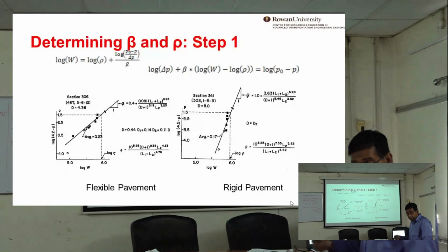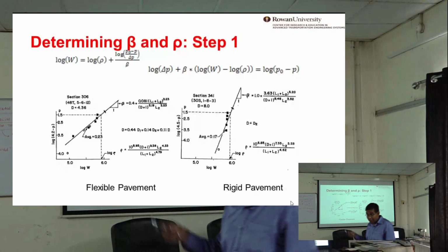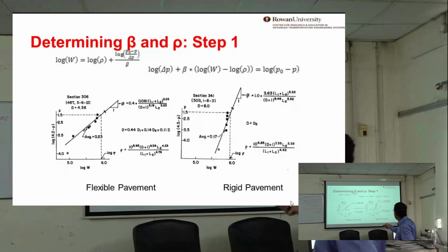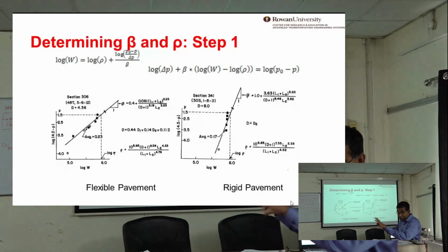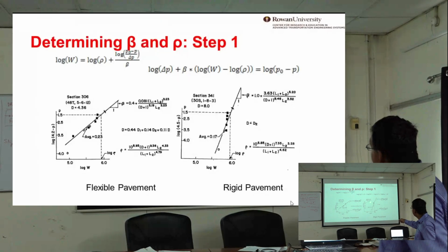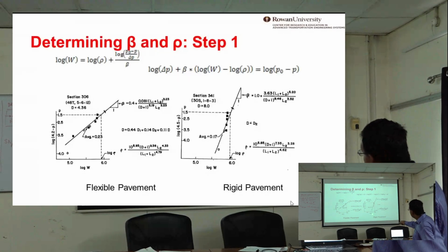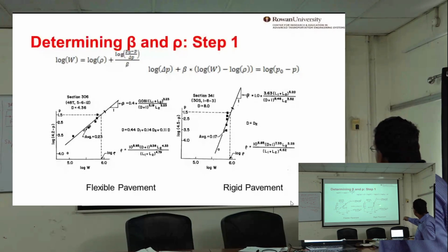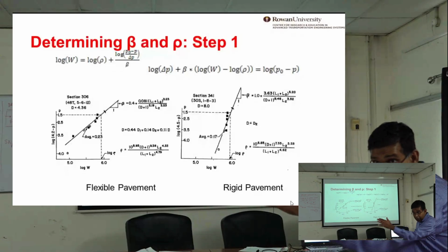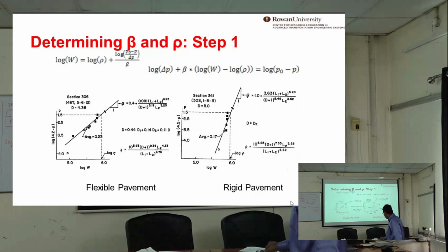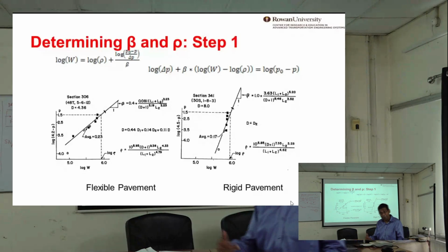So someone was asking me about the model, but this is really the groundwork of the AASHTO. And I've taken just a snapshot, as you can see, from those original reports, right? So section 306 of the AASHTO, section 341, and now they fit the data with the log drop in serviceability 4.5, and now they have different equations formed, and that became the nomograph that you are finding. This came from a question from my students, just like you are asking.